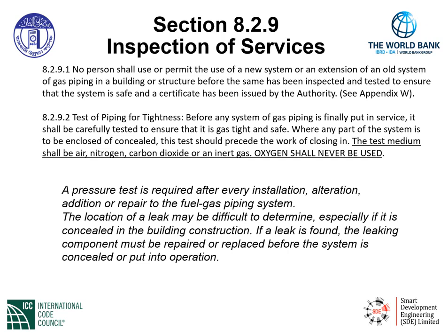The location of a leak may be difficult to determine, especially if it is concealed in the building construction. If a leak is found, the leaking component must be repaired or replaced before the system is concealed or put into operation.